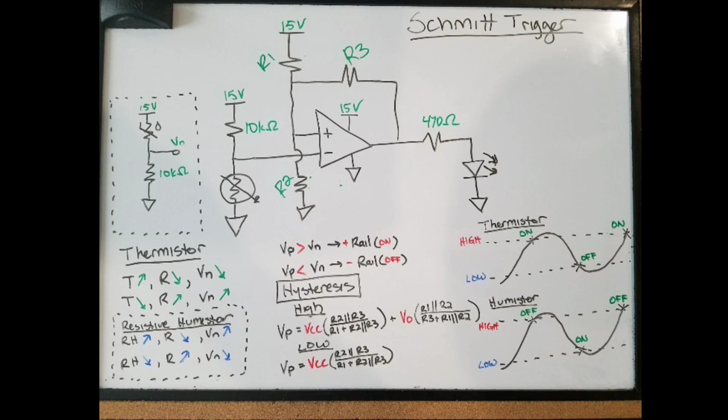And with an op amp connected to a 15 volt reference, that's roughly around 13.2 to 13.6 volts for the output voltage. And when you're low, because the op amp is connected to ground, it's ideally 0 volts for the output voltage. So you only have the VCC, the reference voltage. So that creates a difference that VN must overcome or undercome, go over or under.